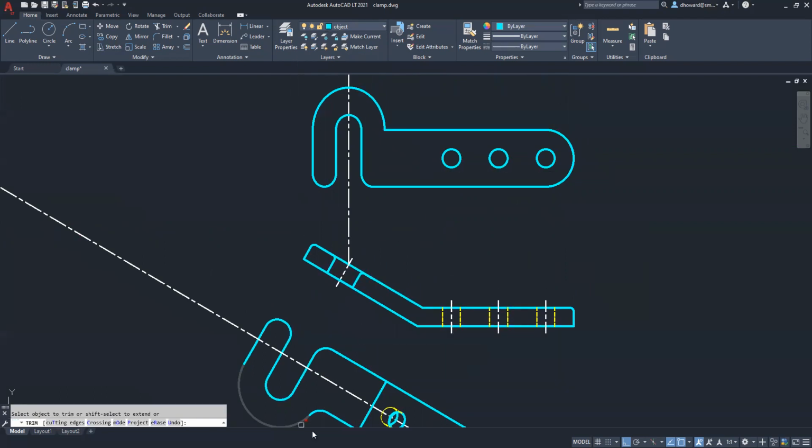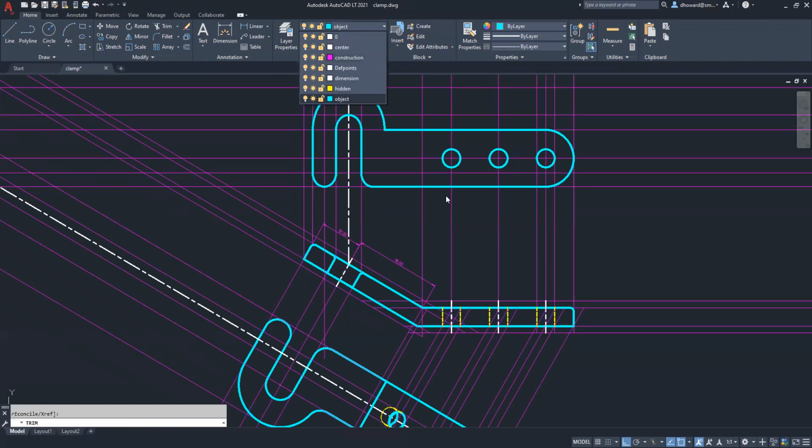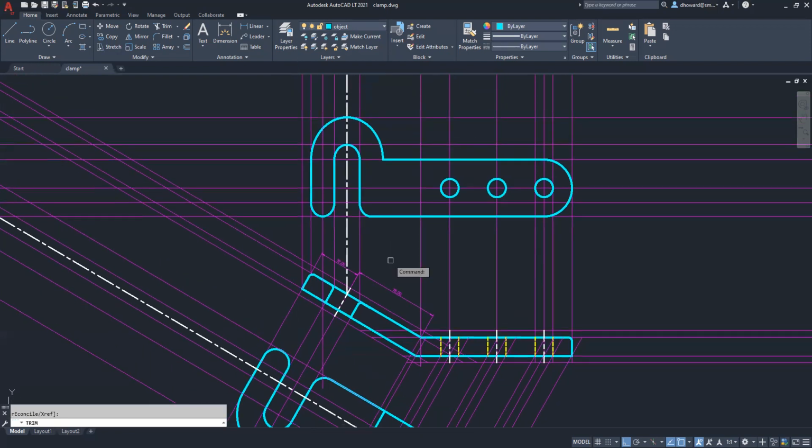We got to do this guy. So again, what would be a normal fillet on this side is actually an ellipse on this side. So let's turn our construction lines back on and find that guy. So it's a 13 millimeter radius. So the distance from this edge backward would be 13 millimeters.